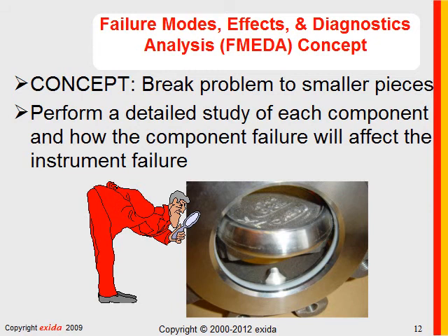Now let me go ahead and make sure you know what this FMEDA concept is. Rather than keep statistics for a product like a pressure transmitter or a valve actuator assembly with pneumatic controls, rather than keep statistics of a device which may have hundreds of components, let's keep statistics on the components.